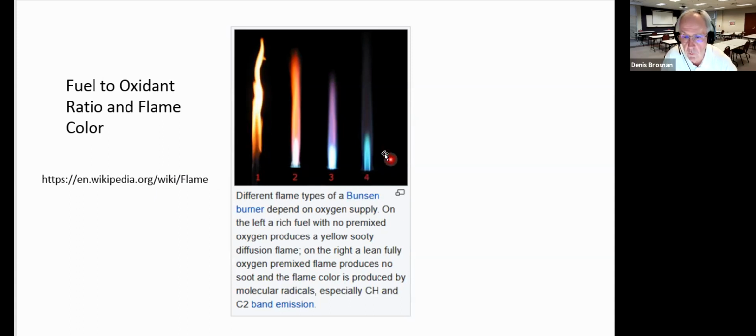Now, even with a blue flame in a furnace, even with stoichiometric combustion, if we have that in all our burners in the furnace, we know that we will have a certain color developed in the furnace. That's the basis of the idea of color temperature of light. And so generally, when furnaces get in the realm of 800 to 1,000 degrees C, they will start to glow internally a faint red color to a cherry red.